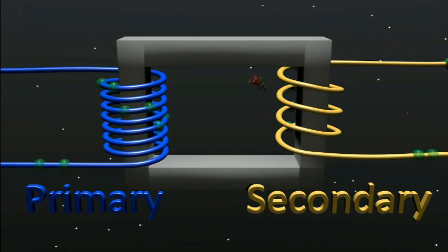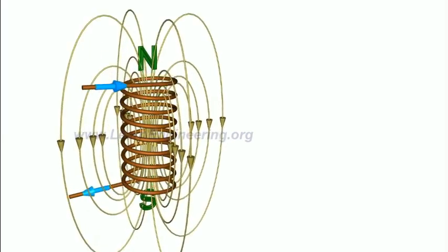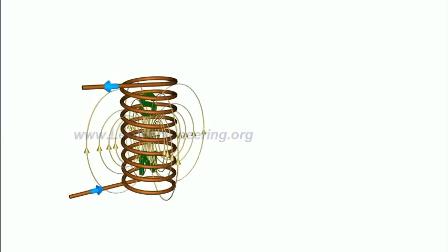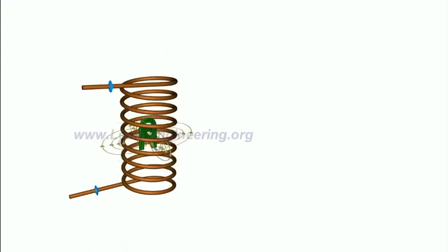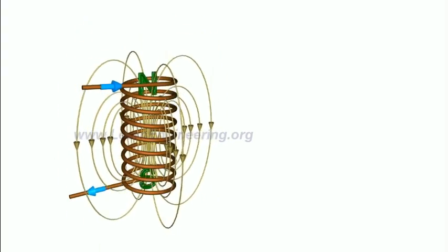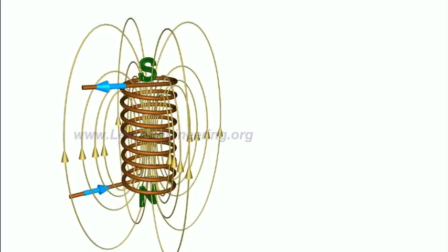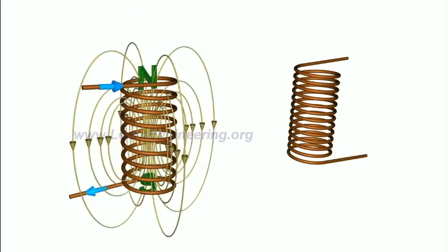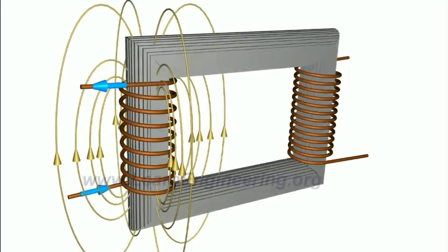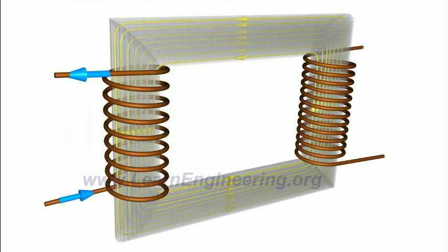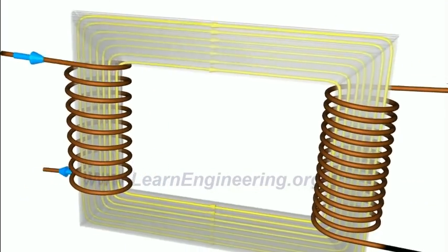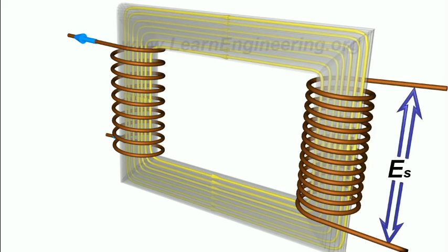Now, as you know about EMI, I can tell you what a transformer is. In a transformer, there is a primary coil in which we pass an AC source current. With fluctuating current in the coil, the magnetic field also fluctuates. This magnetic flux can be linked to the secondary coil with the help of a ferromagnetic material. This alternating flux will induce an alternating EMF in the secondary coil, producing an alternating current in that coil. Now you must be thinking, what is the use of that transformer?